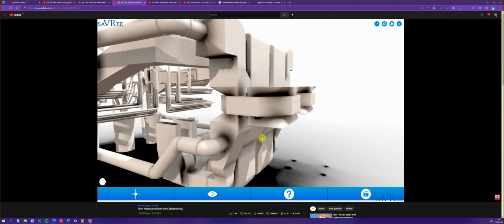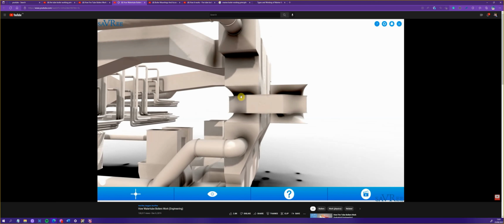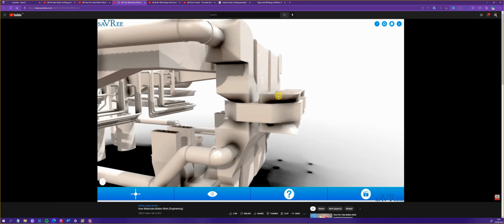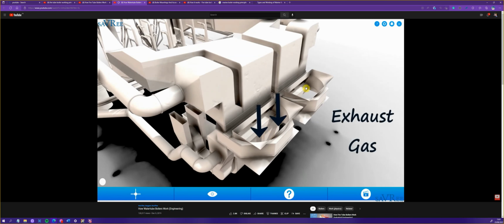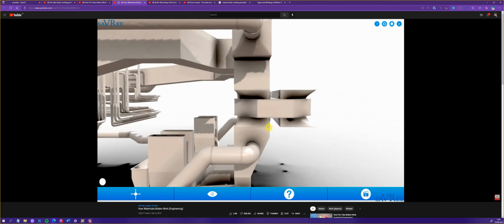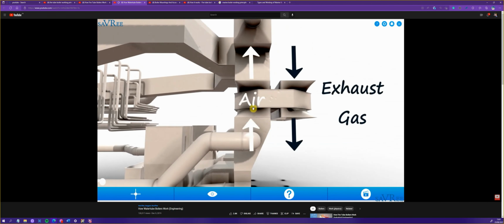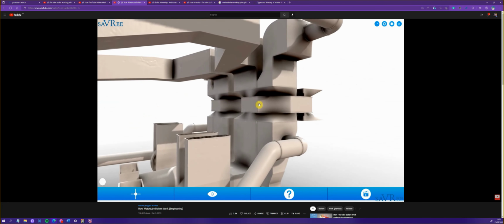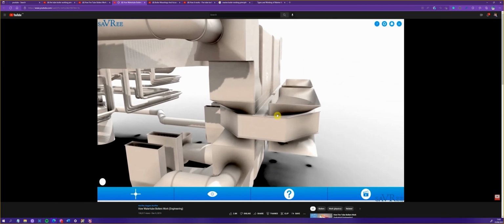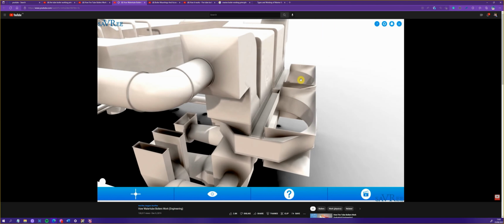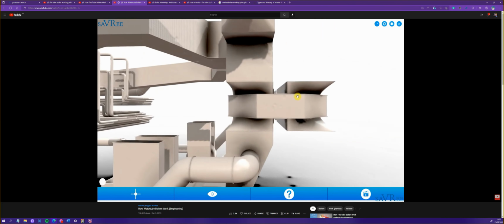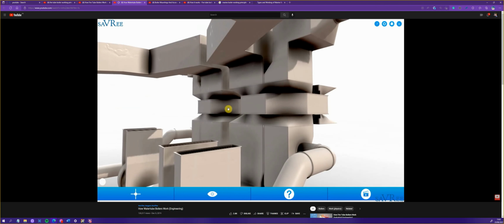This item here is an air preheater. We're going to have exhaust gas coming through here, and same on the other side. And then we're going to use that exhaust gas to heat up the air, which passes on this side. And then the air is going to be heated up before it goes to the boiler. We do this because it improves the efficiency of the boiler. We don't want to blow cold air into the boiler and continuously cool the boiler down. So we'll recover some of the exhaust gas heat by allowing it to be passed to the air, specifically the secondary and primary air systems.